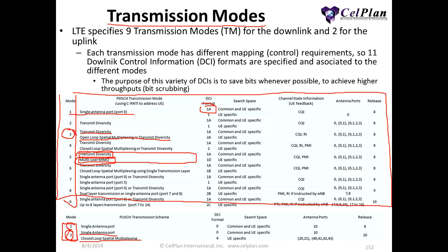So basically, you can do an RRC reconfiguration if you want, and then you say, okay, now we are not 3 anymore, now we are 9, so we will have now beamforming. But that requires an RRC reconfiguration. But the adaptation depends on the type of the message, and if you can use the strongest MIMO or the weakest MIMO, or if it is a message that requires to be sent with the weakest MIMO, because you have to receive it, be sure, doesn't matter which kind of MIMO is used. So that's the adaptive part.